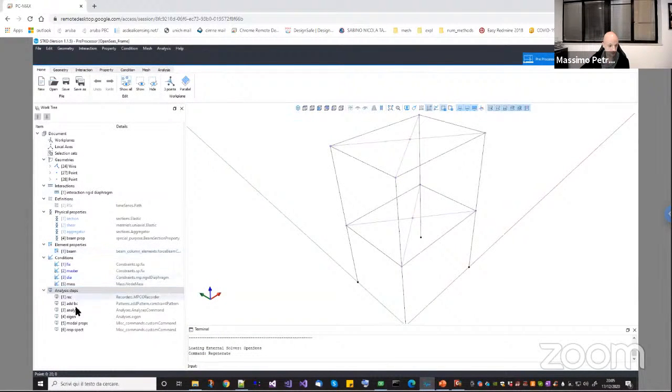Okay, so as I said, first step, the eigenanalysis. Second step, the modal properties. The third step is the response spectrum analysis. Now, once again, I forgot to tell you something. When people do an eigenvalue analysis, they typically just use the eigen command without setting any analysis before. This is fine.